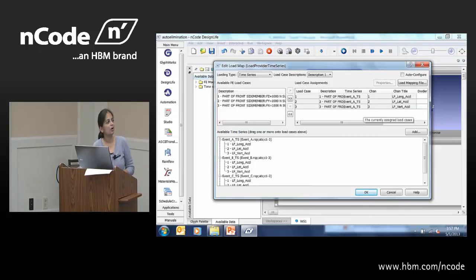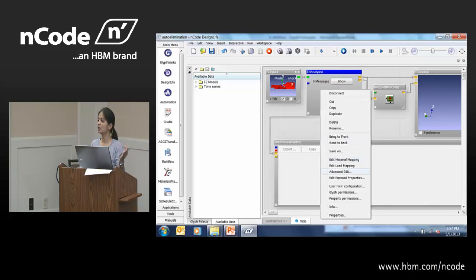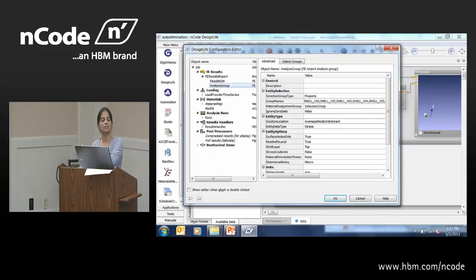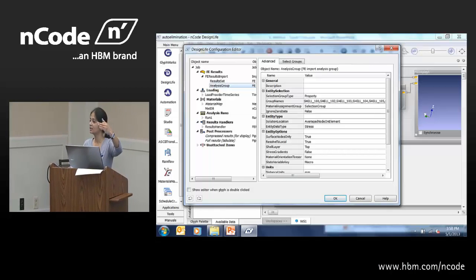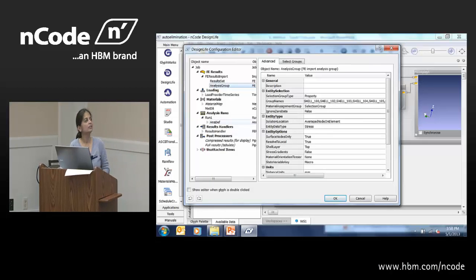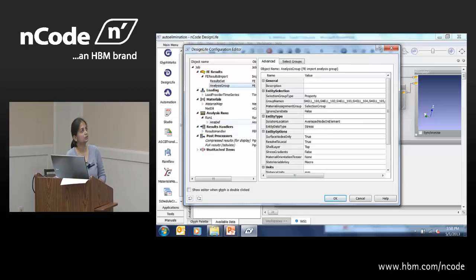By default, all glyphs are set up with 1 run, which runs the damage calculation on the whole model using the entire time histories. What's beneficial is to add a filter run above this damage calculation to find a list of critical nodes or elements. Before version 8, you would have to do this manually. Now there's a wizard to help you do that.